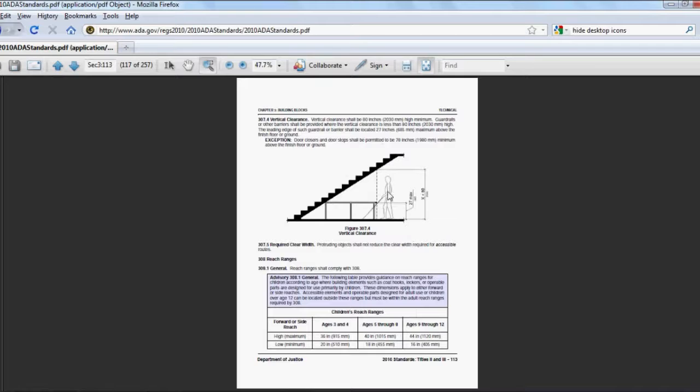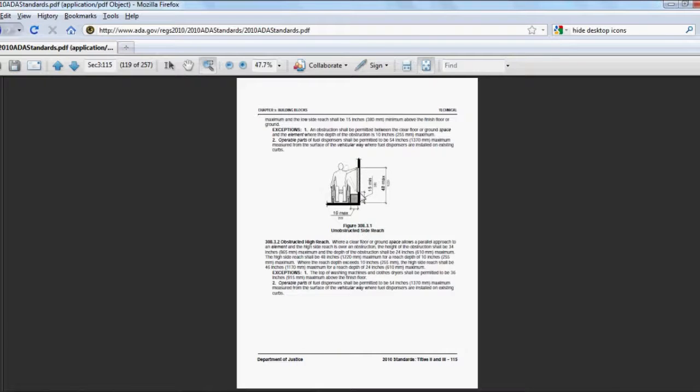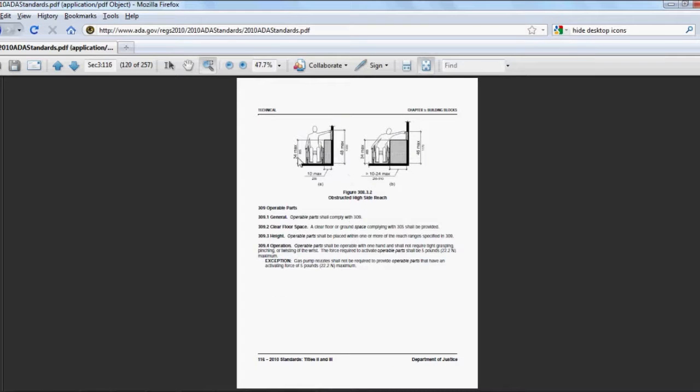The reason that no stair ever quite makes it all the way to the ground in a public space is that somebody with a walking stick needs to be able to identify before they hit their head on the stairs that there's something above them. So all of these codes, all of these standards are out to protect people who are wheelchair bound or physically handicapped.